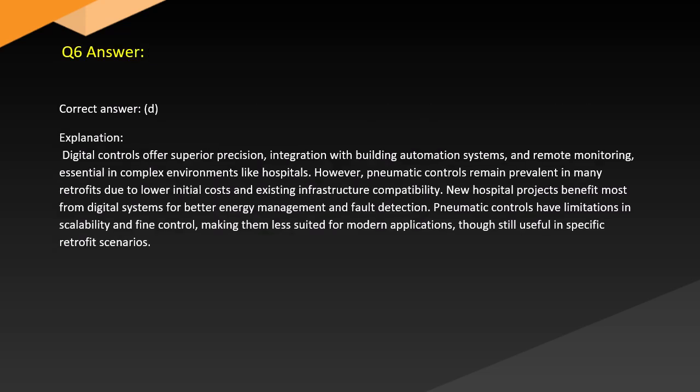Answer. Correct answer: D. Explanation. Digital controls offer superior precision, integration with building automation systems, and remote monitoring, essential in complex environments like hospitals. However, pneumatic controls remain prevalent in many retrofits due to lower initial costs and existing infrastructure compatibility.